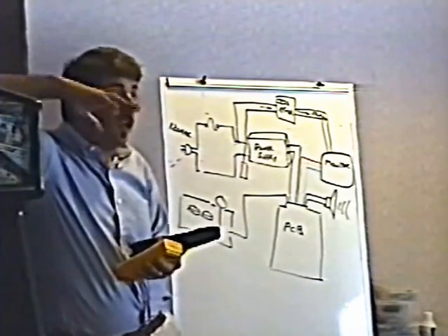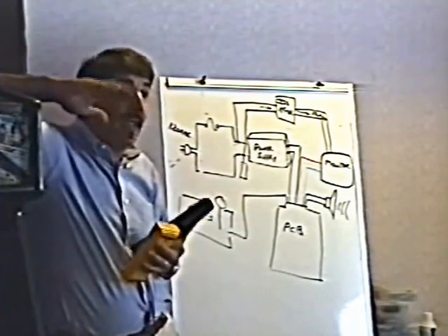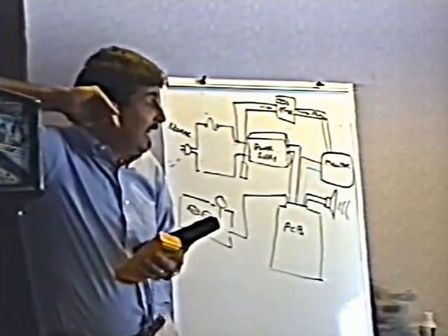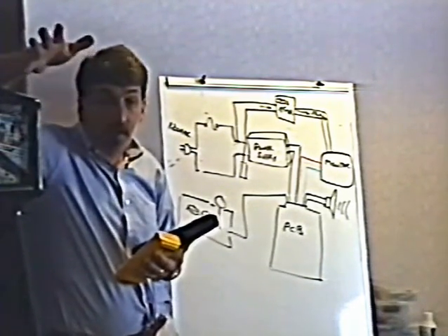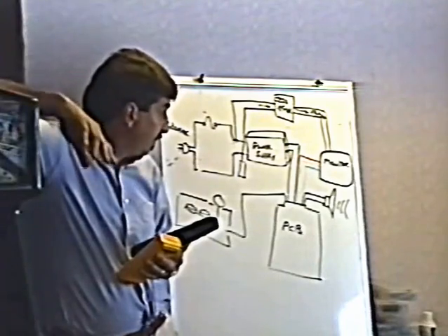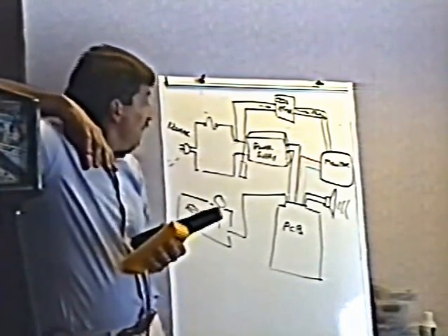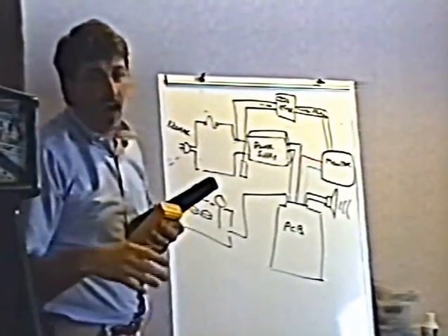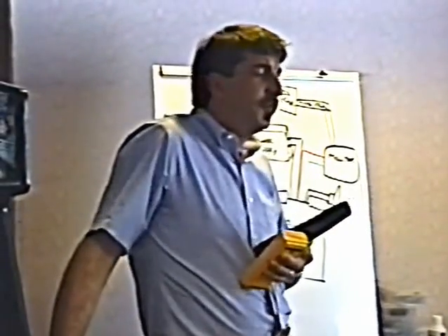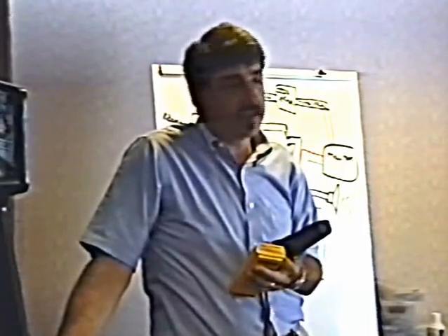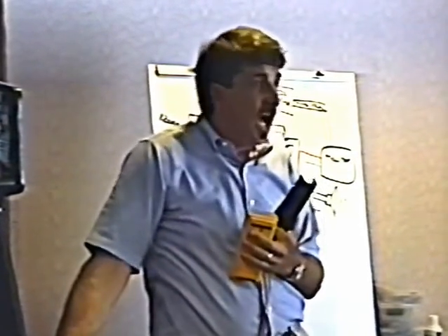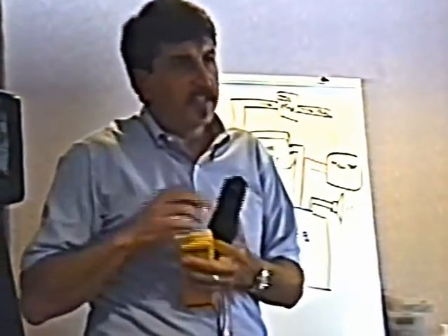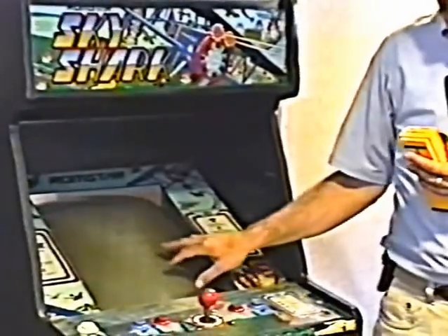So if you get no game sounds at all, you probably have a power supply failure. If you get all the game sounds but no picture, it's probably a monitor failure. Computer failure will rarely cause a blank screen. When the computer fails, usually what you get on the screen is garbage. Jumbled bits of graphics, letters and numbers.